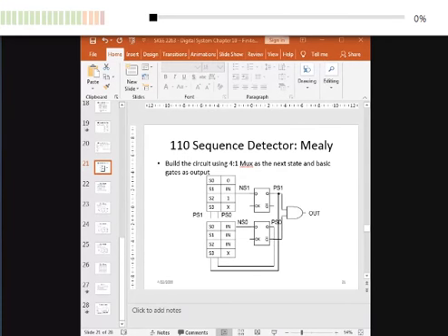But let's assume you are going to interface with hardware, the serial multiplier. You should have 7 segments, 4 units, correct? In fact, yeah, you need 4 units also. You can swap or you can scroll to show multiplier, multiplicand. But then you need result 8 bit, isn't it? 4 by 4, 4 times 4, you should have 8 bit output, correct?